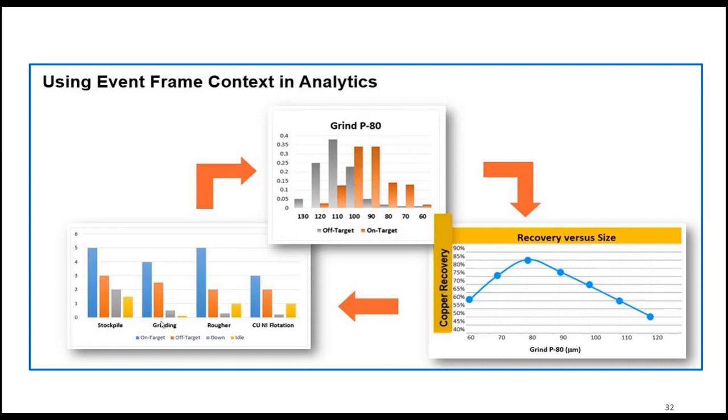But the most important thing is that you need to classify the data sets again. So you have to be in the blue for all this to work. If you are in the orange, you might be able to use it, but you are not 100% sure that the prediction is going to be good. So you classify first, model your soft sensors, and then you optimize and find what are the best operating conditions to get the maximum money, or in this case, the best copper without throwing any copper away in your tails.